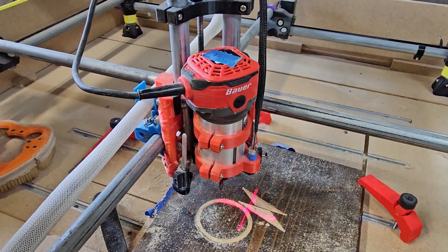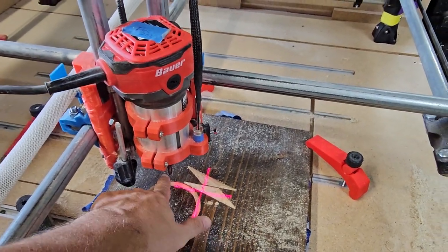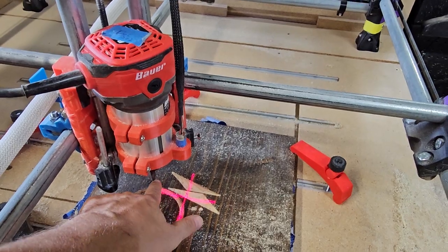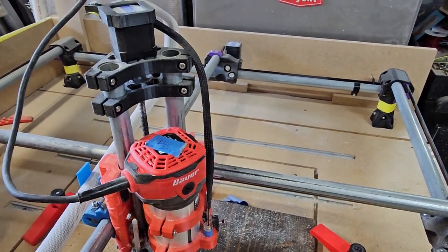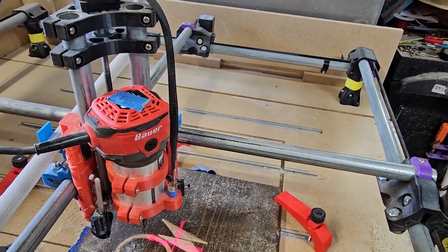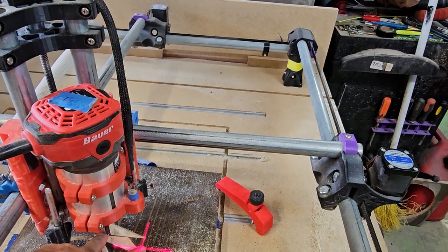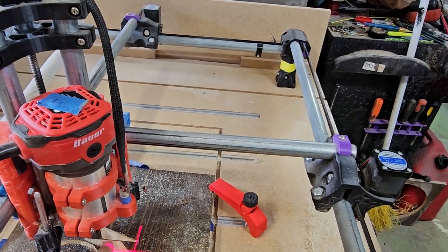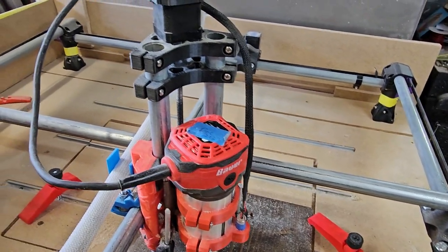So right now, my crosshairs look like they're about in the middle, which you'll see there's a difference between the crosshairs and the tool bit, because my laser is here, my tool is over there. I've got it set up through a macro, a single button push. It moves the bit directly onto where that laser was, because I've measured and I know the difference between here and here. Now you turn the laser off.